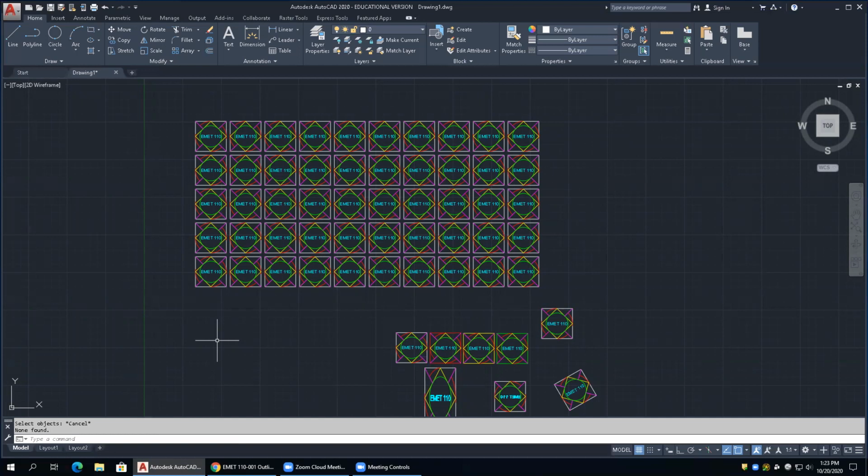Base allows you to set the base point so that when you insert a block from another drawing, it's using that as a handle. Otherwise, it uses whatever your current base is, which is usually 0, 0, 0. Okay. Usually 0, 0. Okay. Any questions?